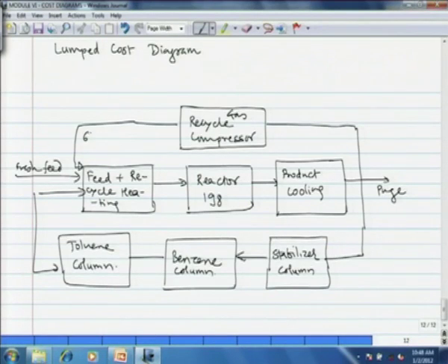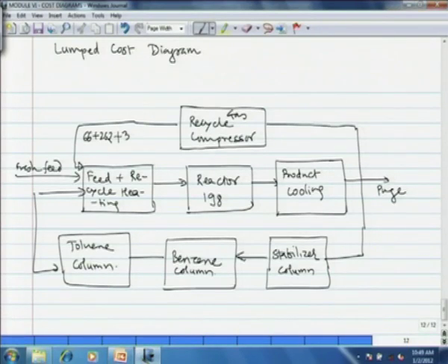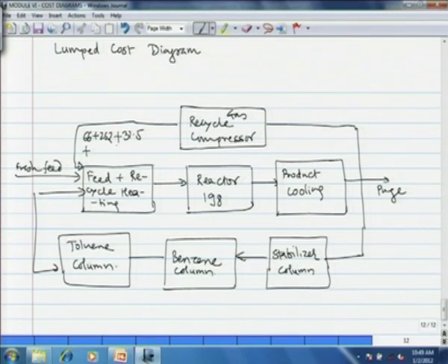So we write here 66 plus 262, plus we had one heat exchanger that heated the recycled toluene, $63,000, but we have allocated the cost equally to the 2 streams. So 31.5 of that, plus we had another exchanger here that heated the fresh feed, a $41,000 heat exchanger annualized capital cost, and that cost we had distributed as $29,000 and $12,000 to the reactor effluent and fresh feed side. So that cost we also add here, plus 12. Together these make $371,000. Let us take product cooling.